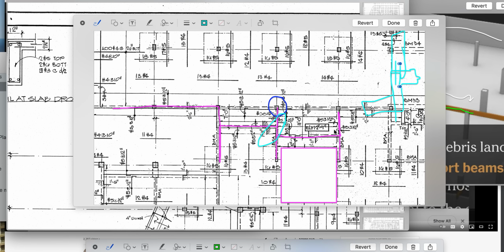It creates a shear plane because this is a staggered break right here, and the deck. Let's go like that. There's your construction joint. These create shear planes. Remember, you guys don't know it. I've been arguing with an engineer who calls me up, saying no, I have these BMAs acting like a shear plane. I don't have it getting to the building that way. You have to go through these BMAs.